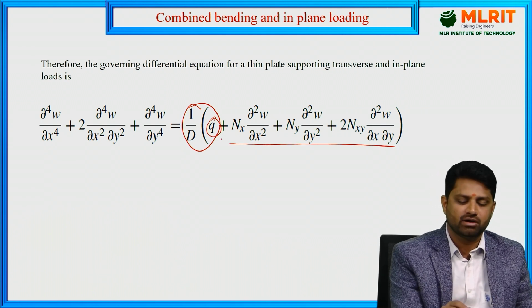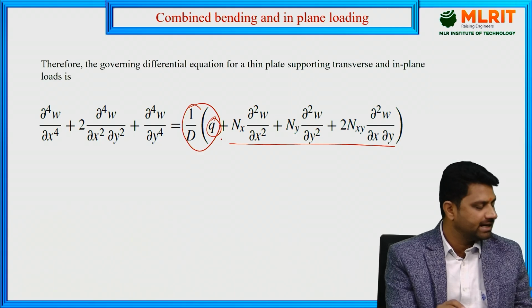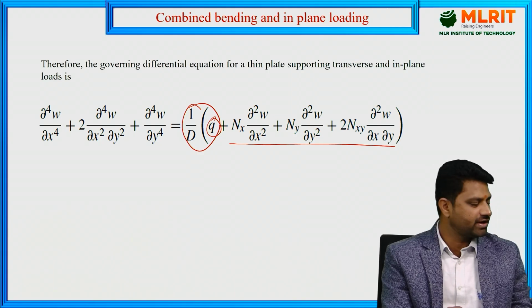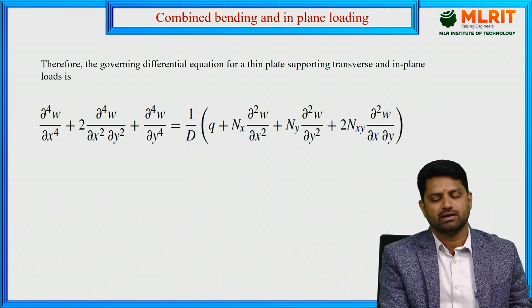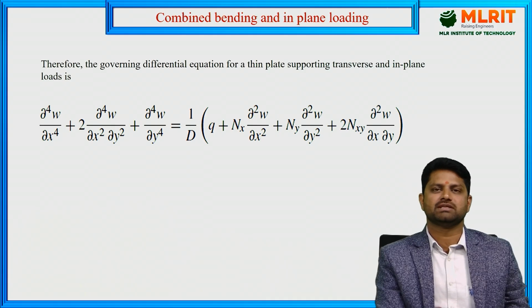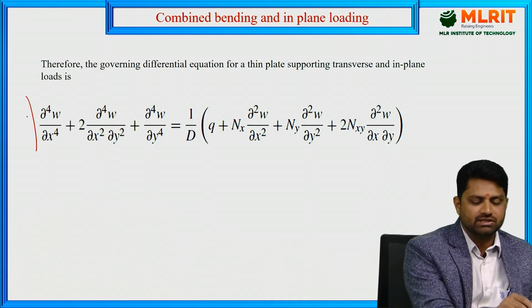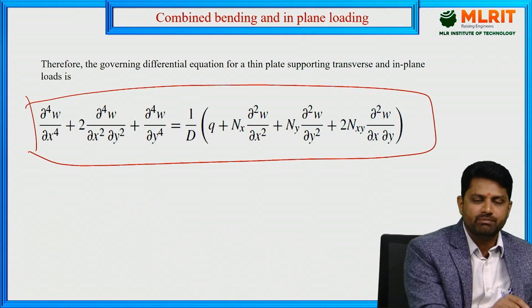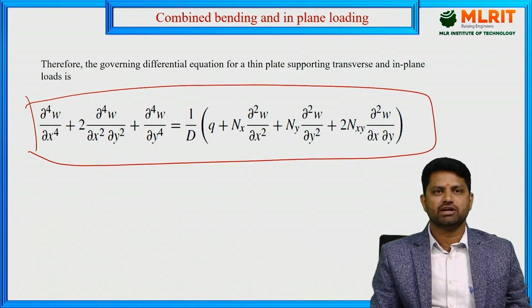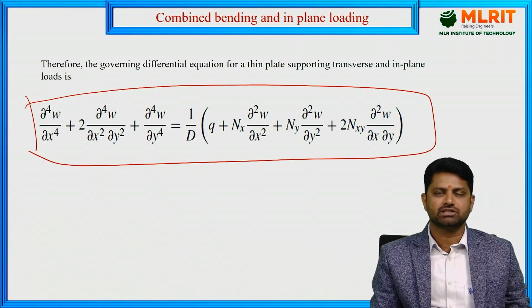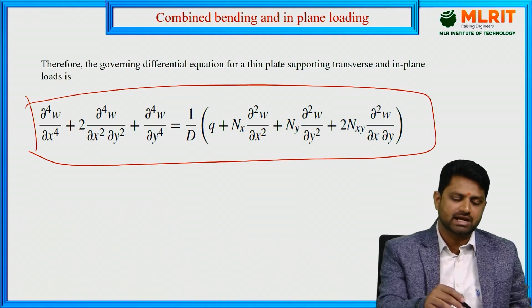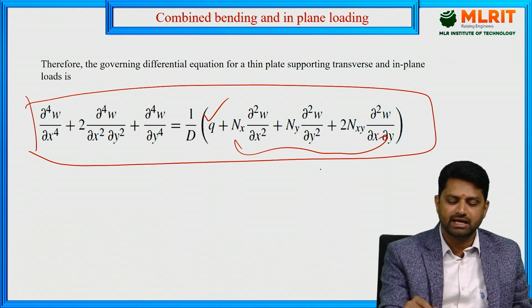So 1 by D of q plus Nx into ∂²w/∂x² plus 2Nxy into ∂²w/∂x∂y plus Ny into ∂²w/∂y². So this equation is a very important equation, because it gives the governing differential equation for a thin plate which supports transverse loads as well as in-plane loads.